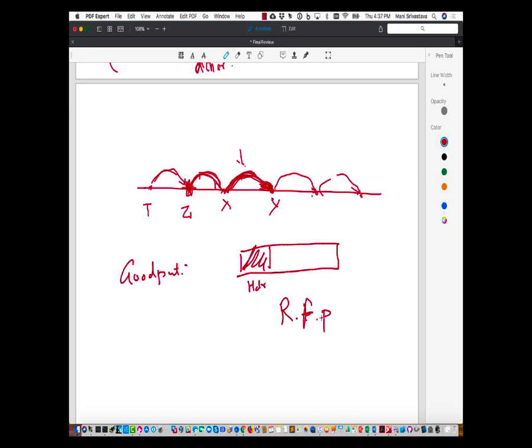But the main thing is that all these factors come into play. There is the overhead of the header. Actually, before that, another thing we had talked about was if my radio was sleeping, then there is a startup time. So startup time, header, all of those things come into play, and therefore the actual fraction of the information that is going through is a function of all these things, right? So if my policy is that if a bit is bad in the packet, I'm going to discard the whole packet. And the other situation is packet collides. When packets collide, then they're lost anyway.